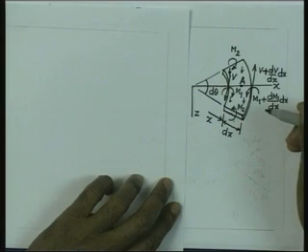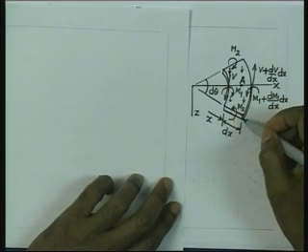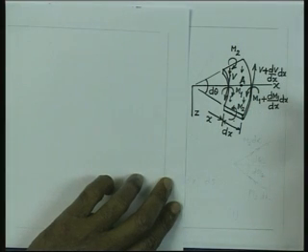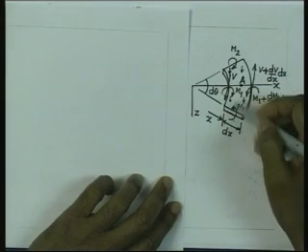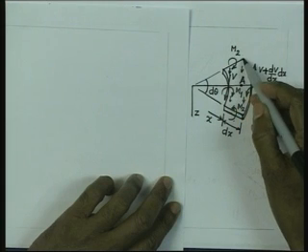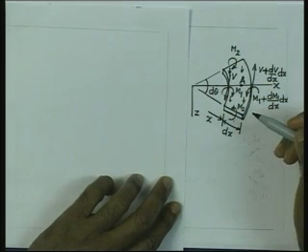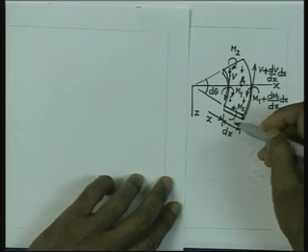Now, can you just think about what about the shear forces coming up on these faces? There can't be any shear force coming on these faces, because the moment is not varying in the theta direction, and therefore, there cannot be any shear deformation of these radial faces. The radial plane will remain always radial, and therefore, there is no shear deformation.